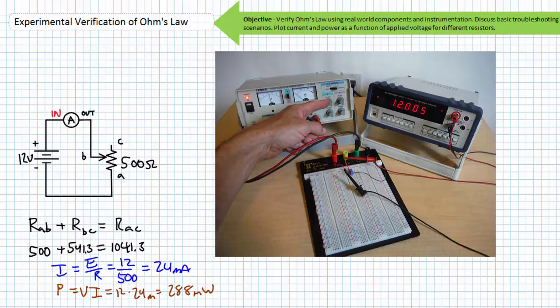It may seem like a pain, but realize I've measured and adjusted the output voltage several times. Once using the analog needle meters on the front of the power supply, a second time using the DMM in an unloaded condition, and a final third measurement using the DMM in voltmeter mode when the circuit is in a loaded condition. The purpose of this successive bracketing is to make sure we're reasonably close to 12 volts when we start and exactly at 12 volts when we're making measurements.